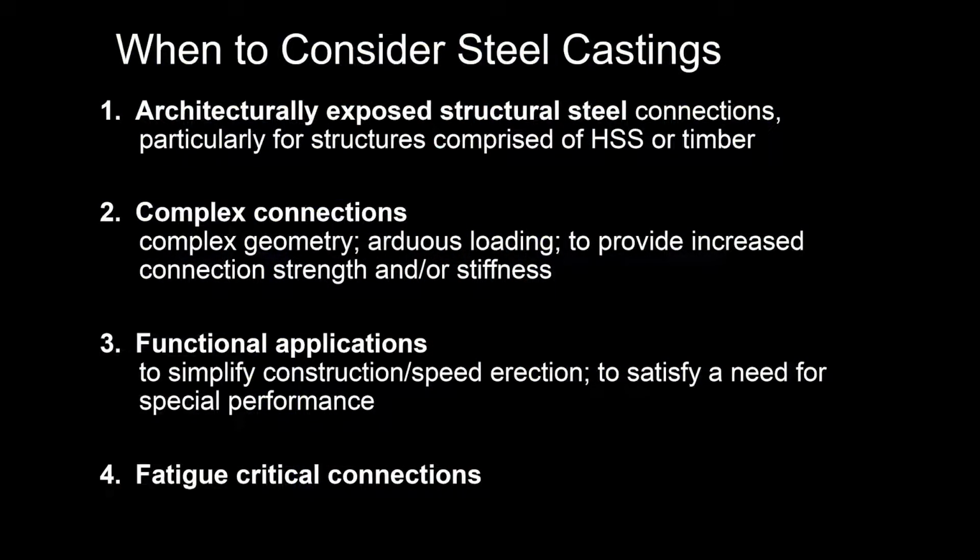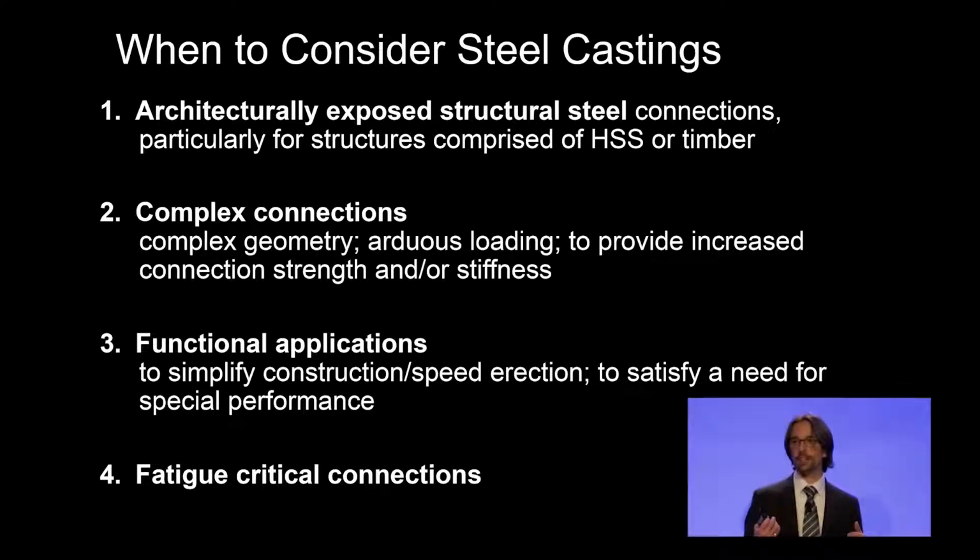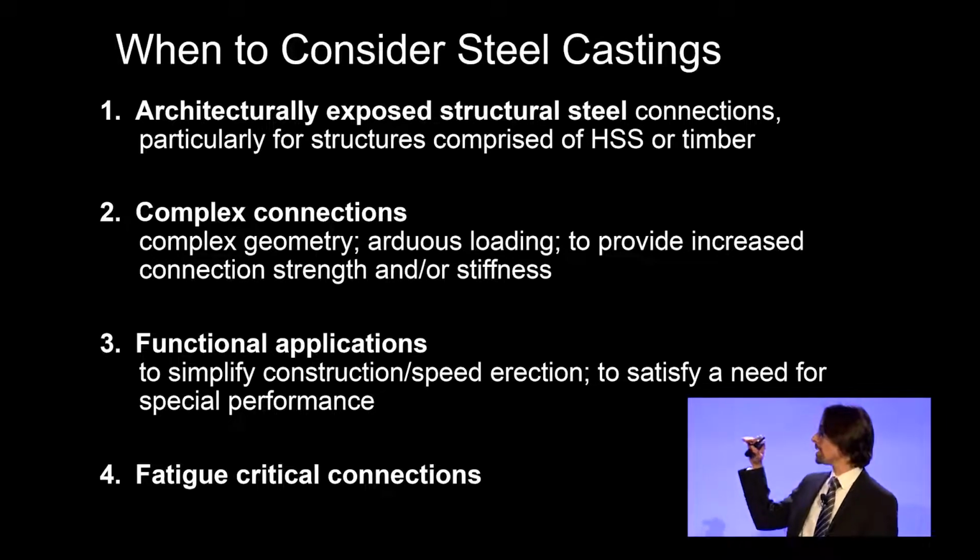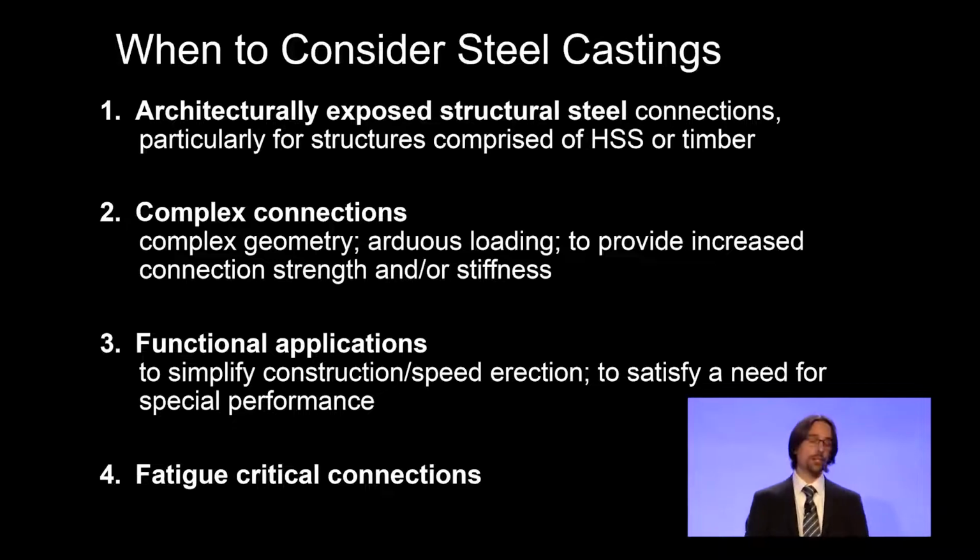So when might castings make sense for your project? Well, there's a lot of opportunity to leverage castings, and the best uses are those that would tick off the most number on this list. Architecture exposed connections, obviously, particularly if the connections or the members framing into the connections are tubular sections, because those are typically difficult to connect anyway. And so with the castings, we can simplify those structural connections, but also express the connection.